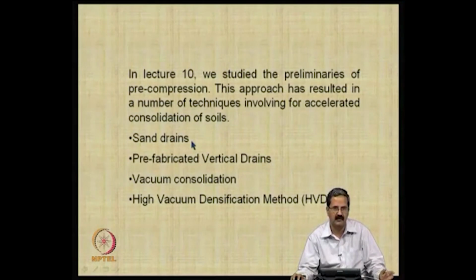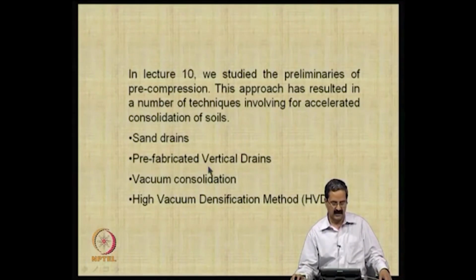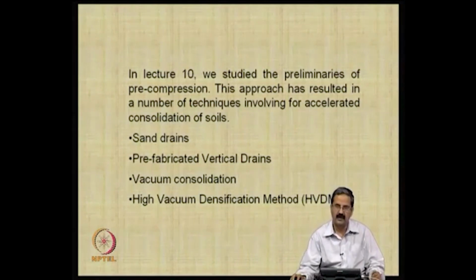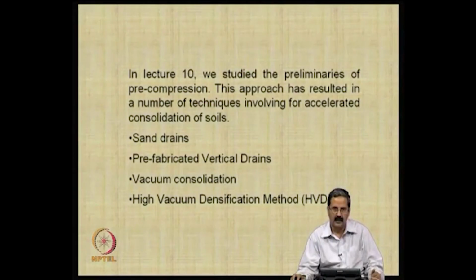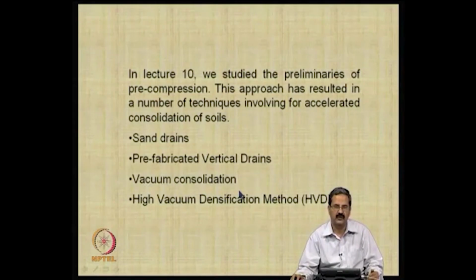Number one, the availability of material itself like sand. The second thing is the way it can be done, the speed of construction could be much higher if you see the prefabricated vertical drains. You saw it in the video that it can be very good, and wherever soft soils exist, you have these prefabricated vertical drains installed all over the places to take care of the loads that are imposed.